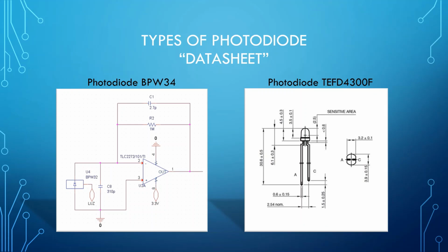It has high sensitivity to the infrared spectrum, with filters to block visible light. It has a spectral range of 700 nanometers to 1070 nanometers. The max power dissipation is 215 milliwatts, with inverse and direct current of 115 milliamperes.